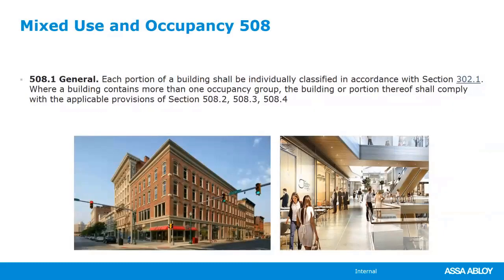And then the fun part, you have mixed occupancy, where you've got more than one within a building that share the building. There's 2 ways to look at mixed occupancy. If the two or more different occupancy types share means of egress components, then your hardware needs to be selected based on the more restrictive requirements.